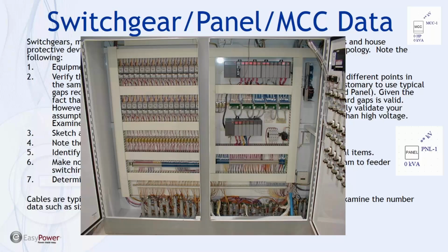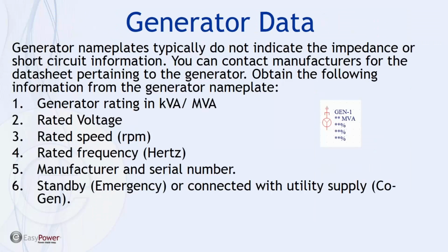In any case, you need to understand, and this is an example of where any voltage connections from a main breaker, if there's not a barrier between me trying to work on this bus and the incoming 480 volts, then I can't utilize the trip characteristics of that 480 volt panel breaker.